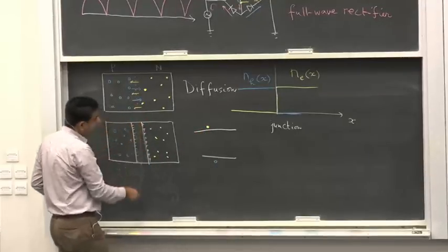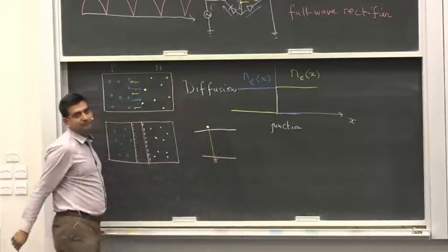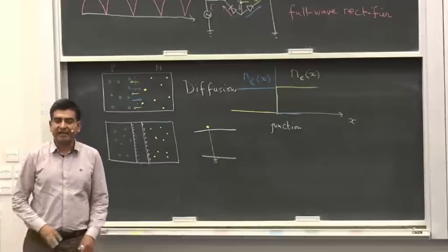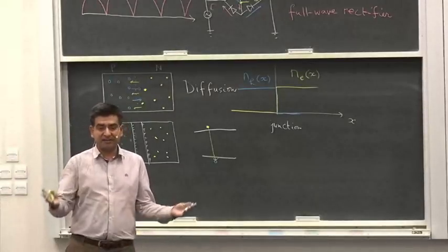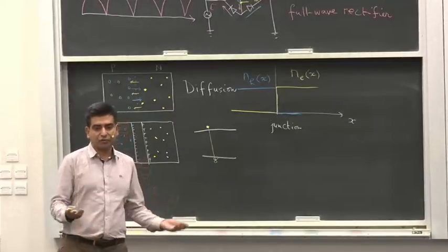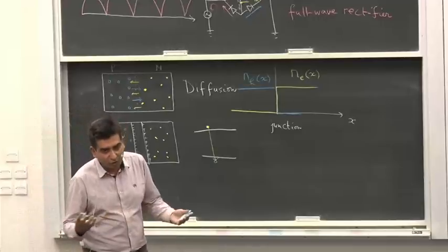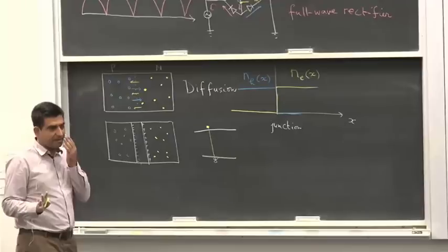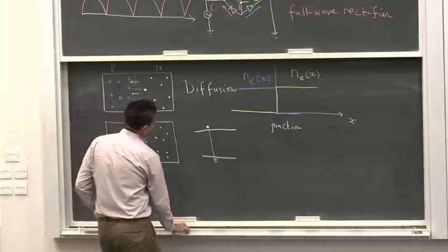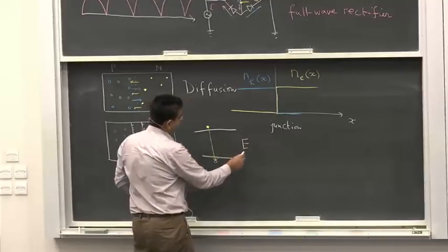What's happened inside this region is that this electron has dropped into the hole and given off its energy. It can give off its energy in a number of ways: light, photons, heat, phonons, the vibration of the crystal. It loses its energy somehow. This process is called electron-hole recombination. An electron has recombined with the hole.